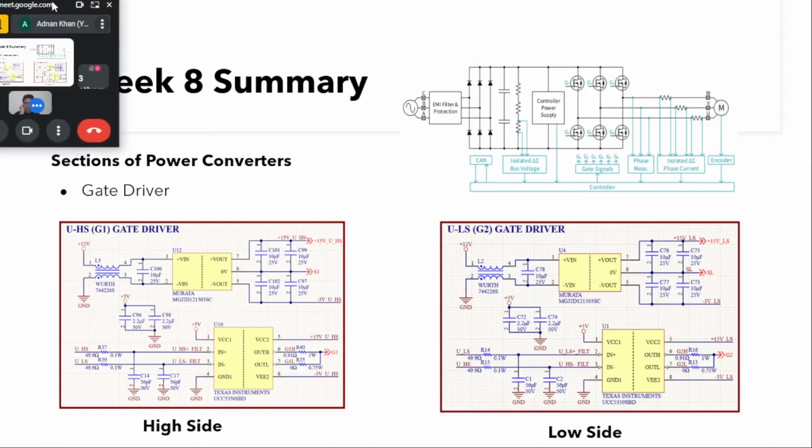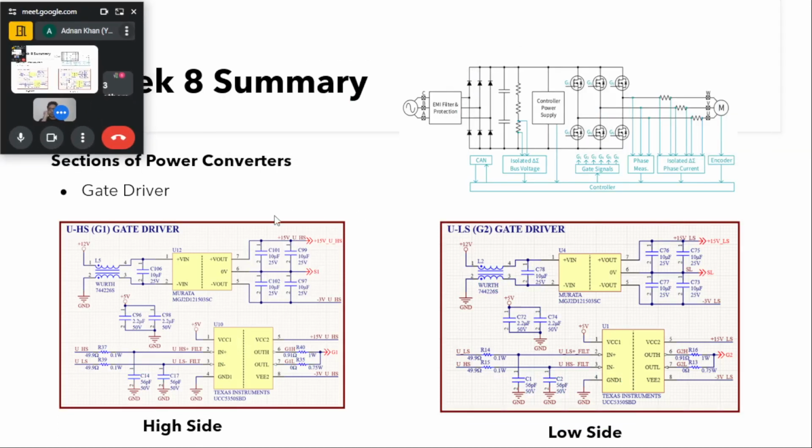Sorry for that, I shall move this here. So now moving to the second part of this converter, we have the gate drivers. Towards the left is the uncontrolled AC/DC, which forms the DC bus. Then we have the controlled three-phase inverter, and we require the gate pulses to operate these switches and to generate a proper voltage in order to drive this motor.